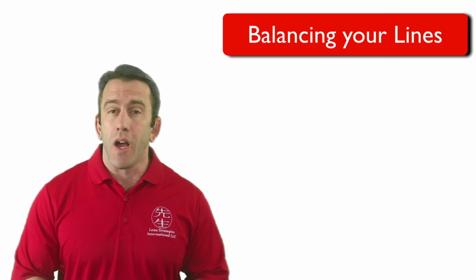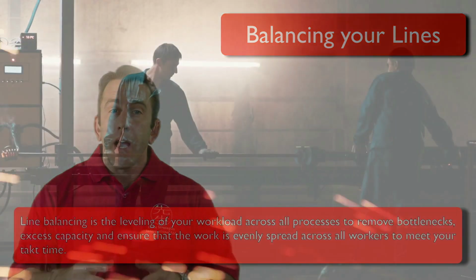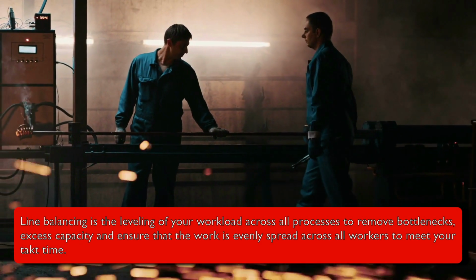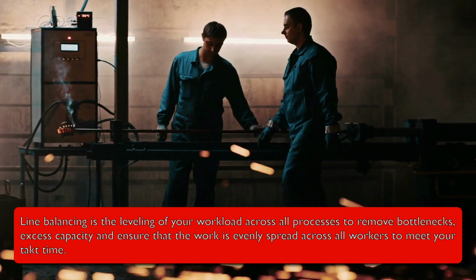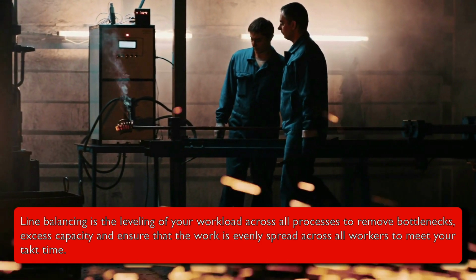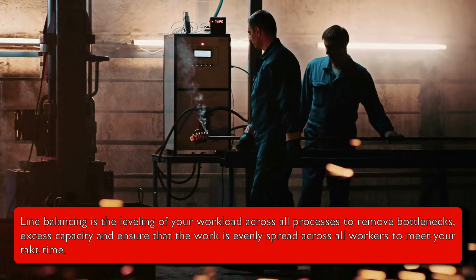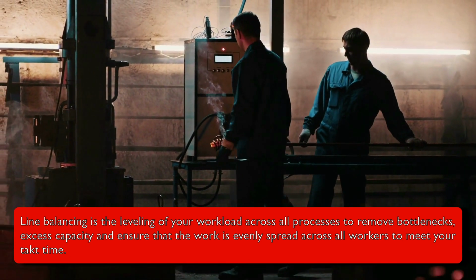If you're going to implement pull in your organization, you need to ensure that all of your lines are balanced. Line balancing is the leveling of your workload across all processes to remove bottlenecks, excess capacity, and ensure that the work is evenly spread across all workers to meet your takt time.